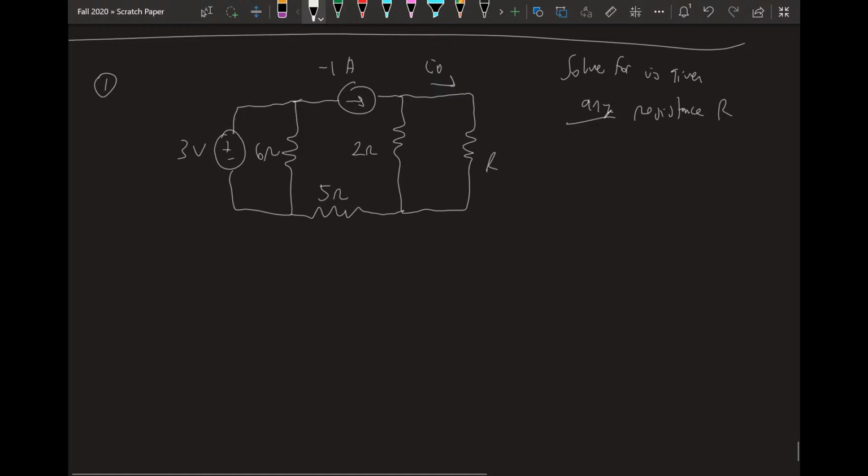Thevenin's theorem states that we can solve for the effect of a circuit across any load by finding its equivalent. So what we want is the effect of the circuit across the resistor, terminals A and B. So when we do that, we essentially remove it from our equation and just find the effect of the circuit across the terminals, and then we'll add it back in after we have found our equivalent. I'm going to solve for all three, V Thevenin, I Thevenin, and R Thevenin, independently. In practice, you would only need to solve for two of them and then find the third. But it's still a good check to solve the third independently, and just to know how to anyway.